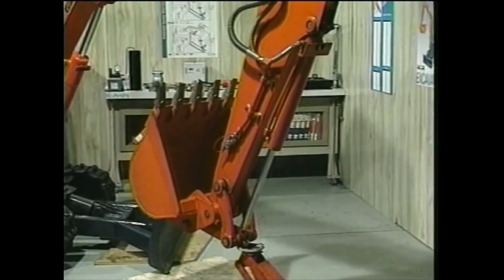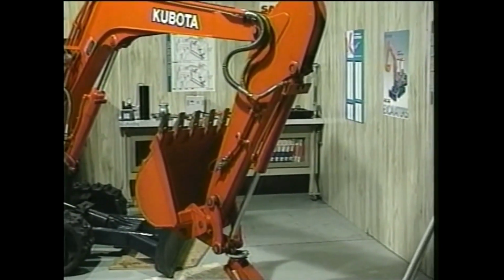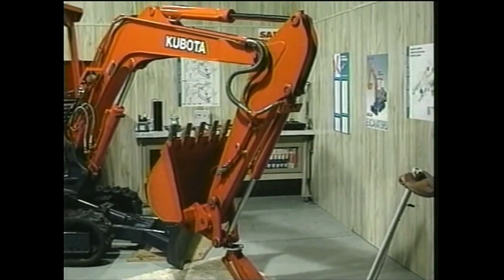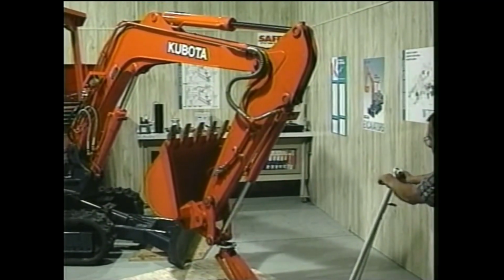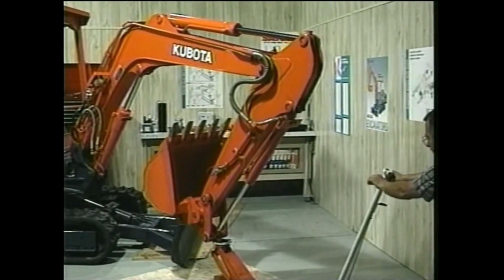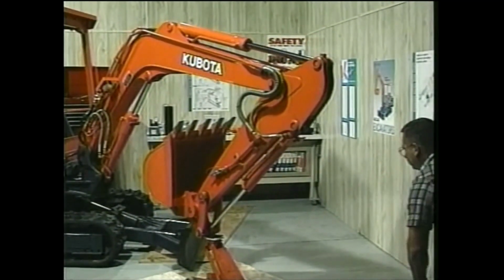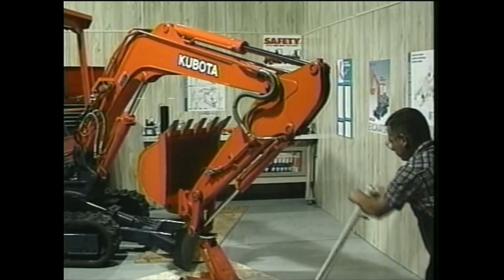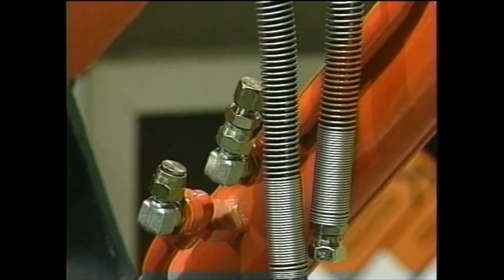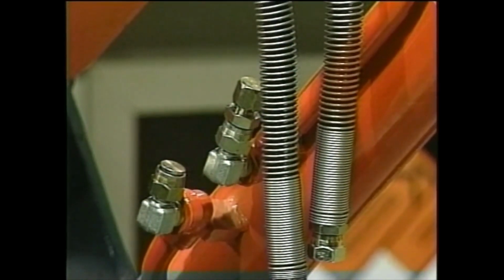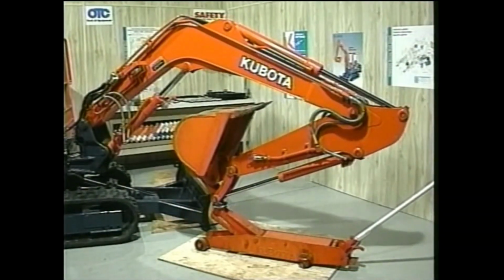Next, the engine is started and the boom's directional control valve is held in the lift position to fill the cylinder with oil. Oil passes by the piston and purges the air on the retraction side of the piston. This removes all air. The engine is shut down. Caps are put on the cylinder hose fittings and the jack is removed.